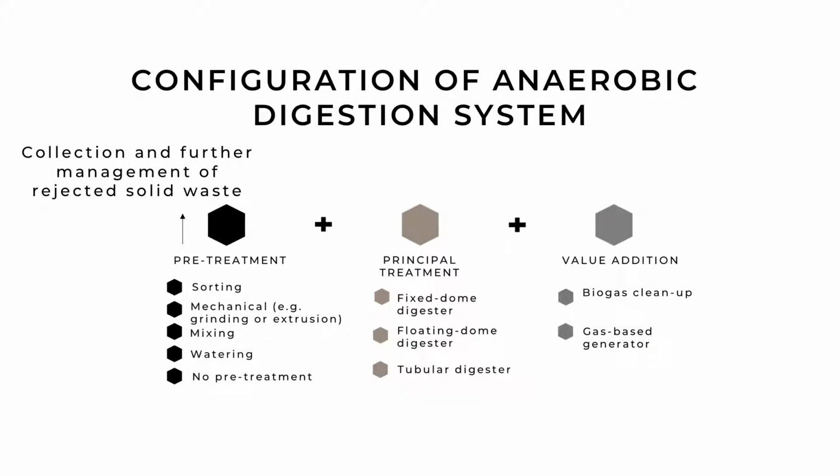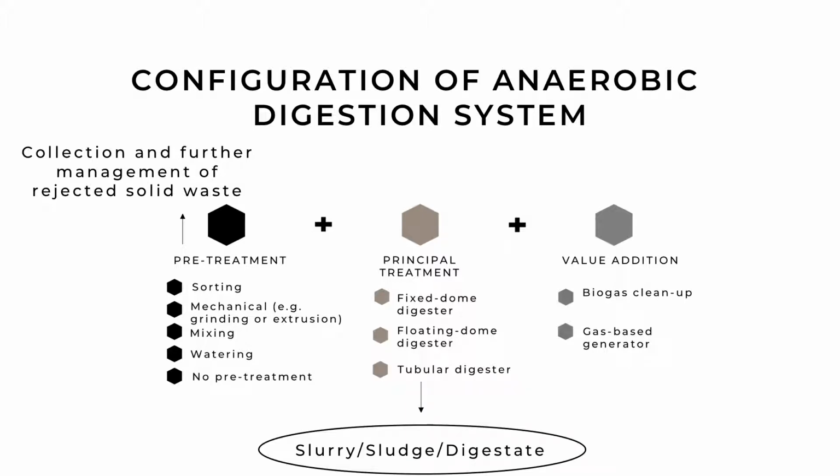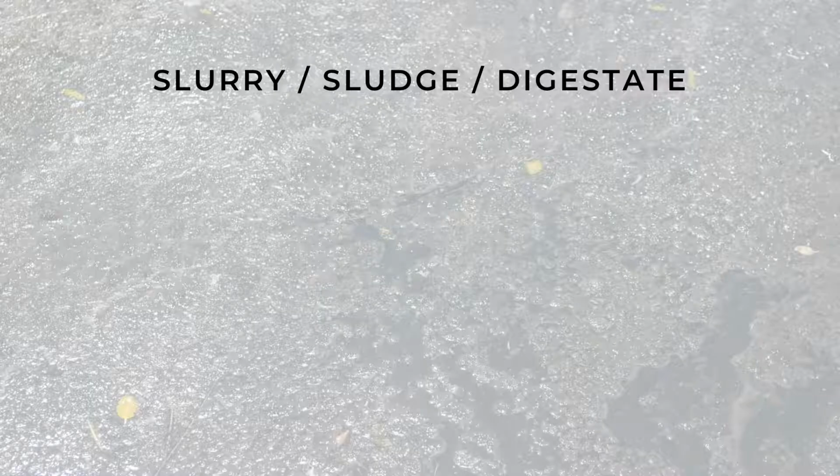Finally, you need to keep in mind that anaerobic digestion also produces slurry, also called sludge or digestate. This end product is rich in organics and nutrients, almost odorless, and the pathogens it contains are partially inactivated. As the goal of our RRR-based business should be full recovery from all end products, disposal at landfill is not advocated. In any case, the sludge has to comply with local regulations and post-treatment technologies have to be implemented.